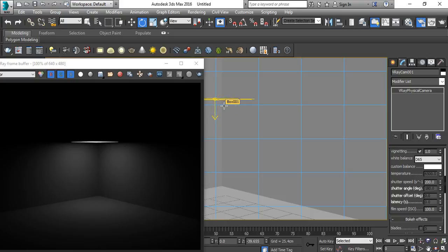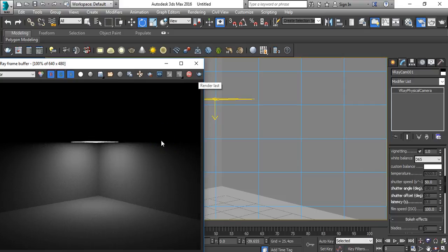Because the light intensity is low and the light is not much here, if you increase the light and later adjust this shutter speed, your scene will burn out. So the good value for me is always 50, and after texturing everything, I see how my result is coming, and then I keep decreasing the shutter speed number. I'm talking about the interior for now. Now you see it's nice.